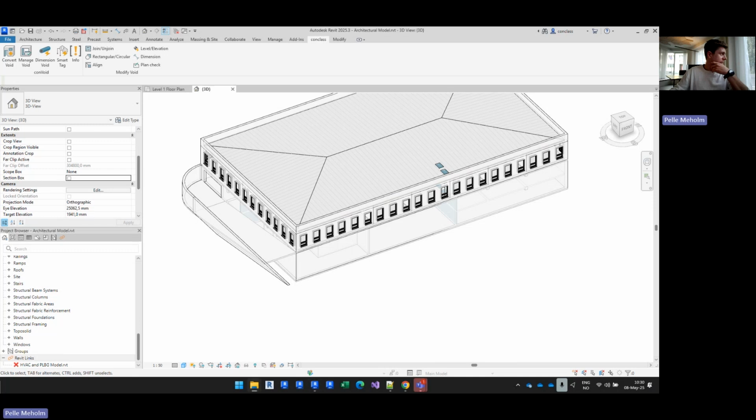Let's have a closer look. That looks great. Now, I'm just going to share my other screen again. The next step is to provide the information to the structural engineer. So that's what I'm doing right now. I'm going to provide him the ISC and BCF file. Since he is not working with Revit, he will use a BCF platform. In that case, we will show you the new Void Manager app, which we are currently developing. But of course, you could also use a different BCF platform.